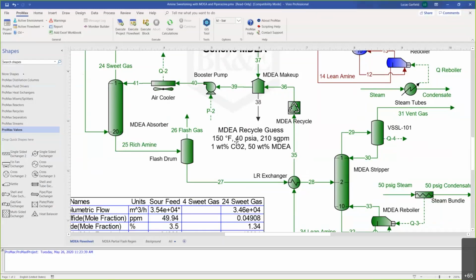But I don't think that it really does very much in terms of CO2 absorption. You're not really going to absorb very much CO2 in just pure water from a water wash. So I would say that in terms of limiting CO2 slip, the water wash is not particularly relevant. I hope I understood the question correctly.